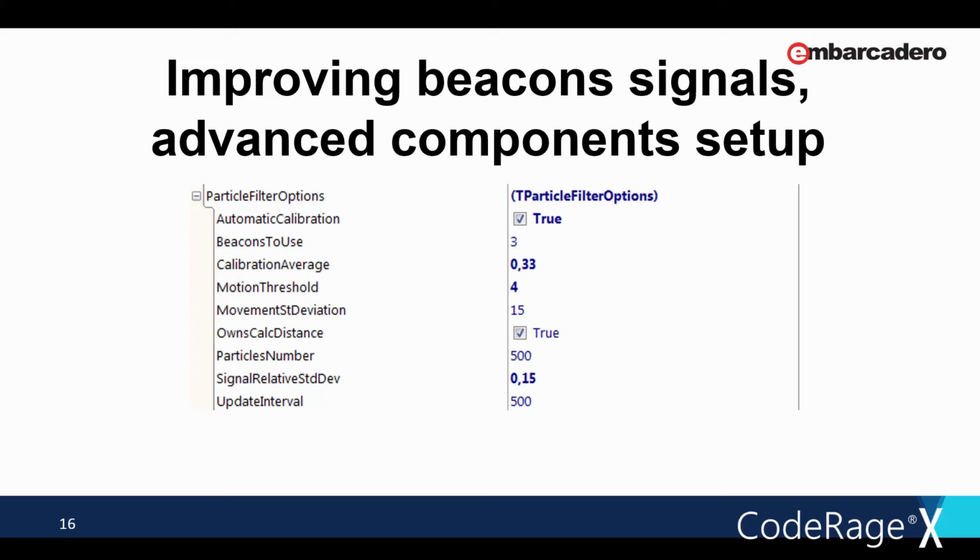Movement standard deviation: at the time of launching the particle prediction, we use the movement standard deviation in order to expand or collapse the point cloud of the MCL. A more expanded cloud gives more possible new location predictions in case of loss, but less stability, and vice versa.